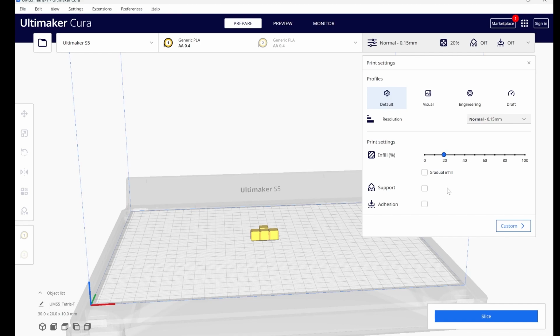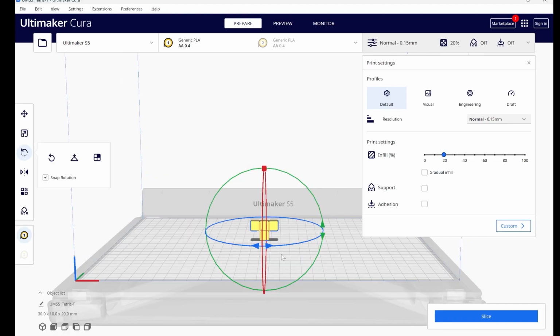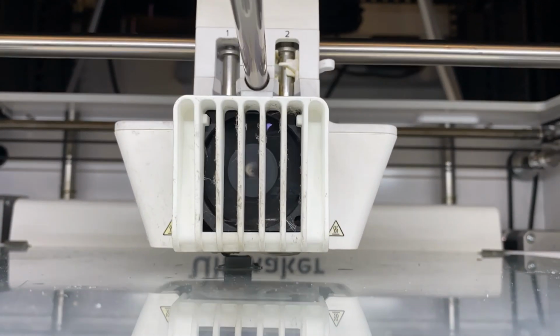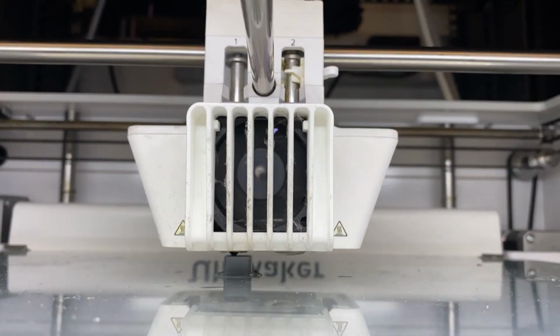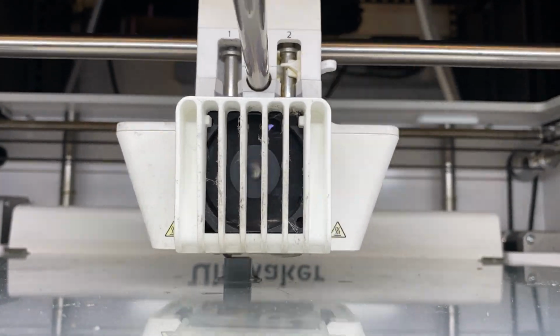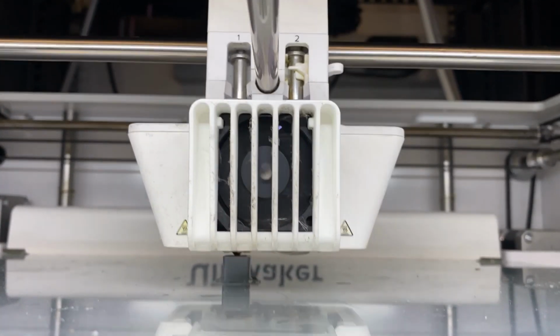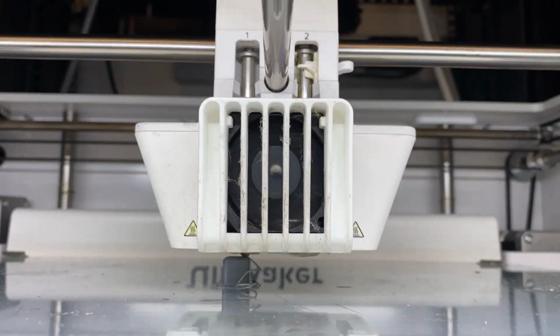You can choose to add support material for overhanging areas of your print. An overhanging structure is one that sticks out without any printed material below it. The printer needs a surface to extrude material onto. Overhangs with a significant angle will cause the print to fail as the filament falls down unsupported.